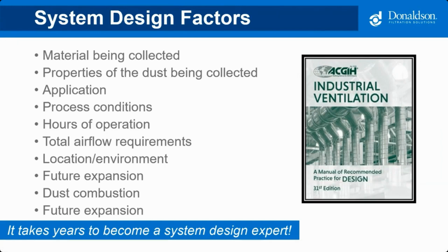The application being utilized, the process conditions, such as, is it humid? Do workers use personal fans? Does the plant or area have conditioned air? What are the hours of operation? Will the system be used continuously or intermittently? What is the total airflow requirement? What location or environmental restrictions exist?